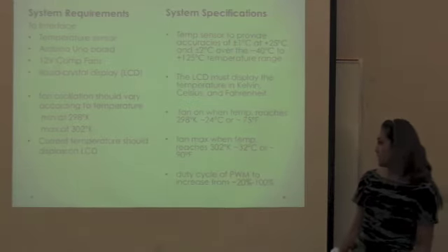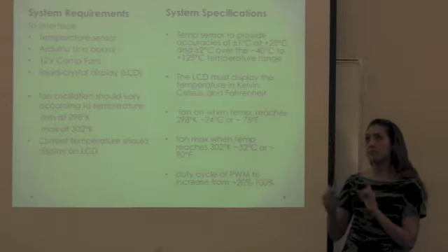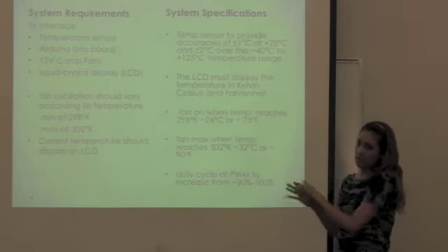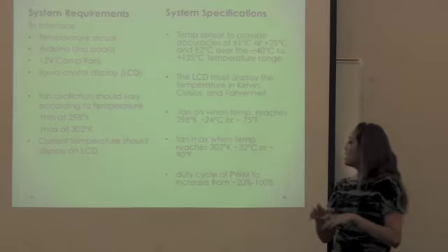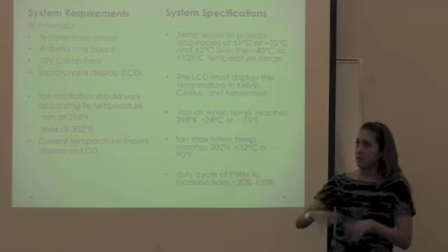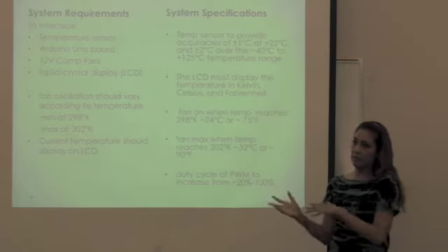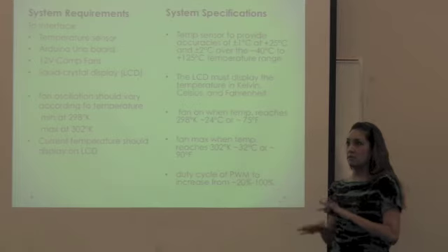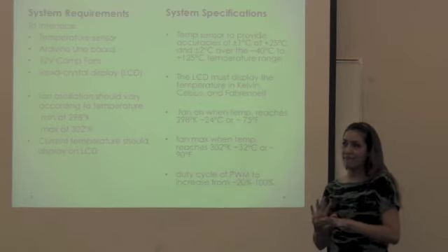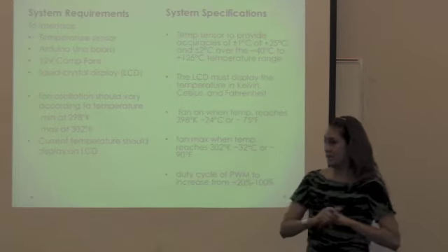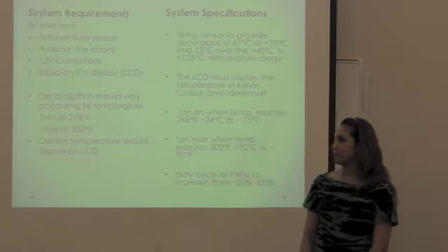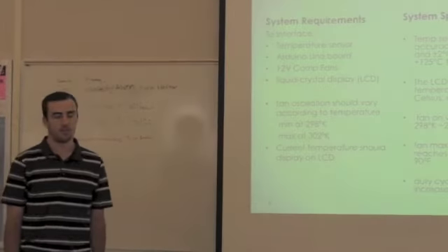And so we decided a duty cycle for the pulse width modulation that we use to control the fan oscillation to be from 20% to 100%, where 100% would be the fan's maximum oscillation. So 20% kind of has something to do with the integration issues.